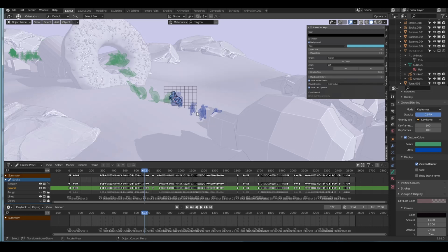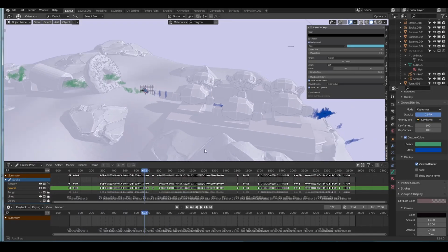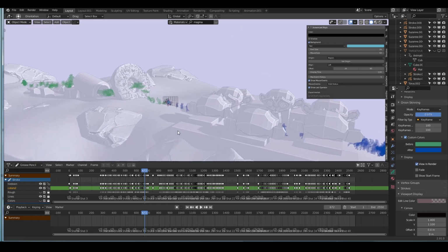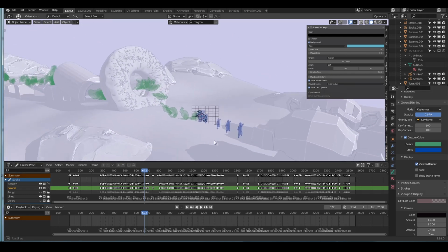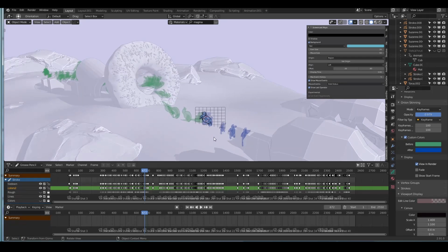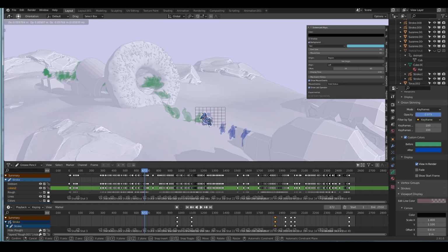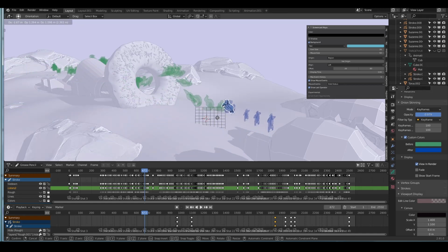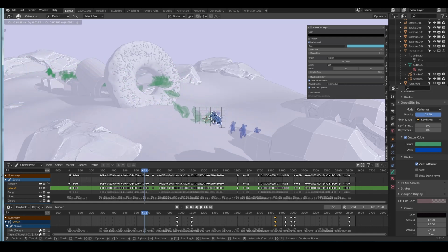If you've done something with the 3D cursor, especially something as extensive as this, where it goes right the way through the environment, then you really don't want to be touching object mode after this, unless you want to completely restage all of the action, right? Because this is what happens. If I grab the object like you would normally here now with G, you see it's not just that, the whole thing moves. This is because the origin is way back at the beginning. So that's what happens.